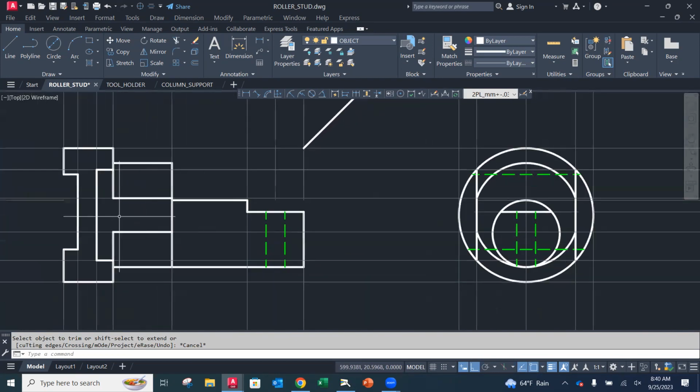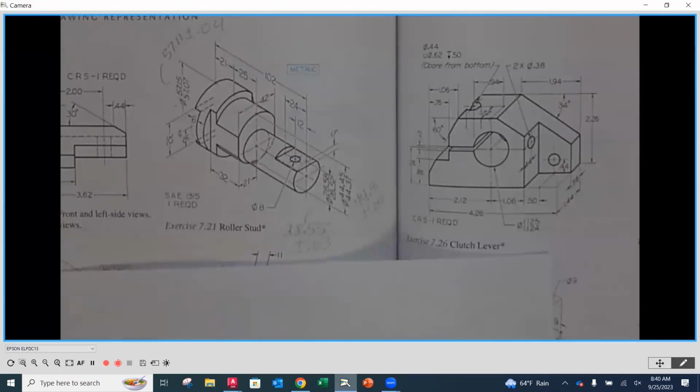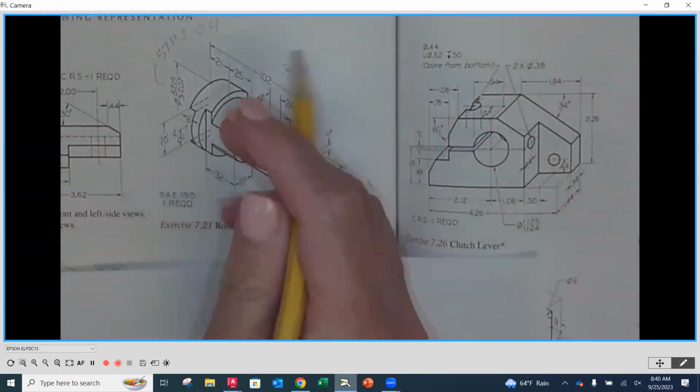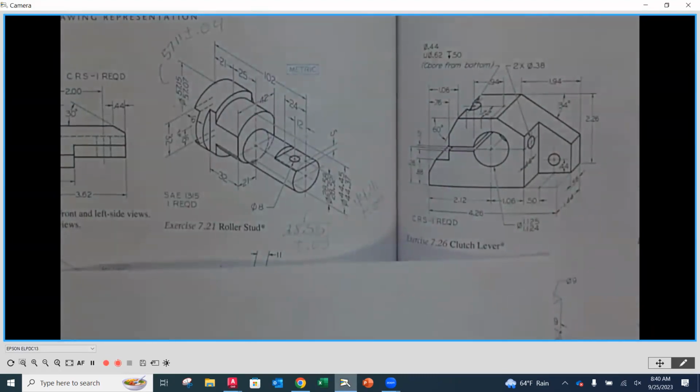So in this front view, then don't forget to get rid of that middle line, because when we look at the drawing itself, because of how deep we are, that becomes a flush surface. So there is no line here. This one went away because it was deep enough and it's like solid material. Okay. So then we just need to translate that up to the top now.